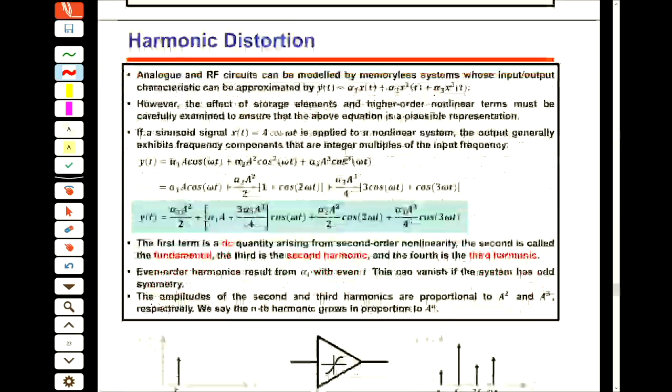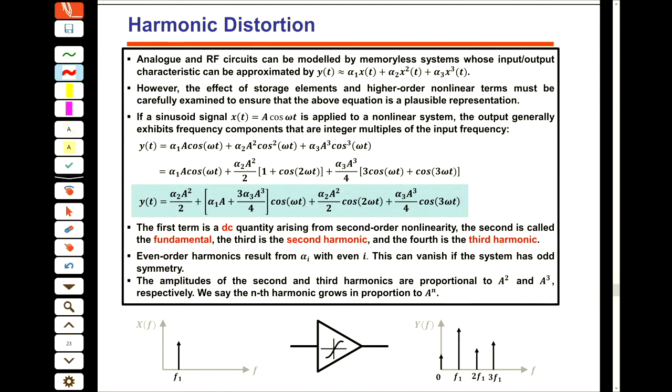Okay, if there is no question, then we are going to the three types of nonlinearities that we have in electronic systems. The first one is the harmonic distortion. The second one is the gain compression. And the third one is the intermodulation. So I'm going to talk about these three, and then I will tell you which one is harmful, which one we can manage somehow. And actually, when we are going to compare two systems, these are the parameters that we are going to compare. I mean, I say that, okay, my receiver's third intercept point, or third intermodulation point, is this value, and for example, his design is this value. So if the third intercept point is higher, then maybe it's better.